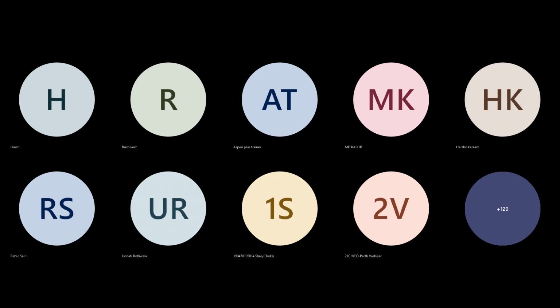इसमें कंट्रोल वाल्व लगाते हैं या कैसे कंट्रोल करेंगे, मतलब orifice? Orifice is one of the option. See, आपको recirculation का flow control करने की या तो provide orifice or you should provide a manual valve. So manual valve is the easiest option. Most of the companies or organizations give a manual valve only. Orifice is also one of the good option if you want a fixed amount of flow rate going in the recirculation line. अगर आपको for example 10 मीटर क्यूब पर आवर का पंप है और 10% के हिसाब से 1 मीटर क्यूब per hour should go in the recirculation line, then you should provide a orifice for that 1 meter cube per hour of flow rate. Flow orifice design करके you can do that.